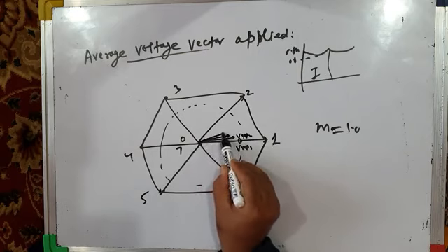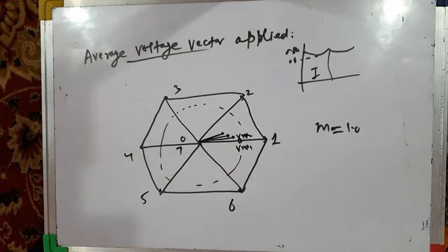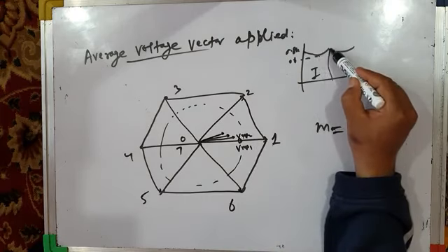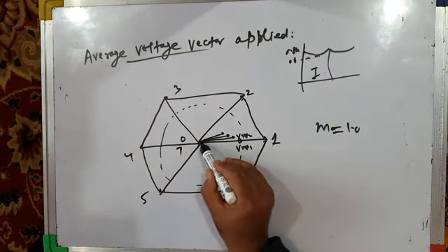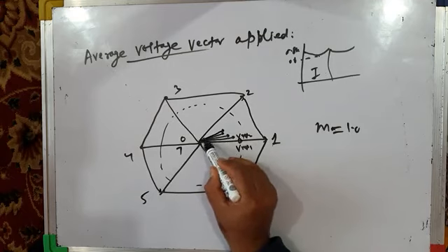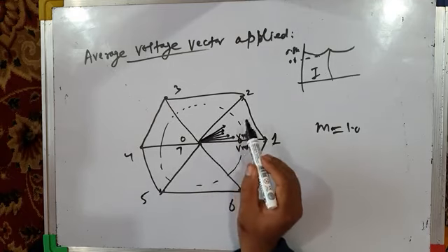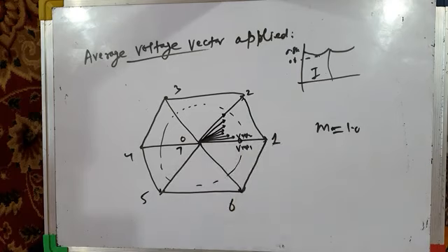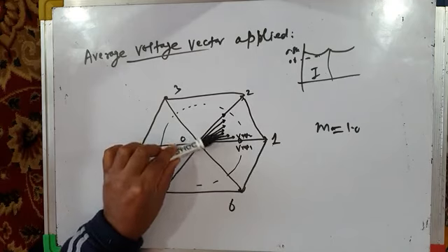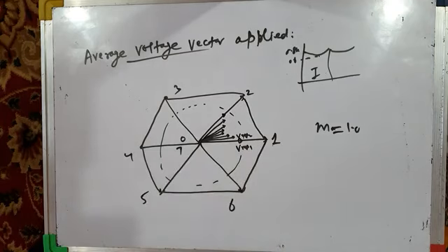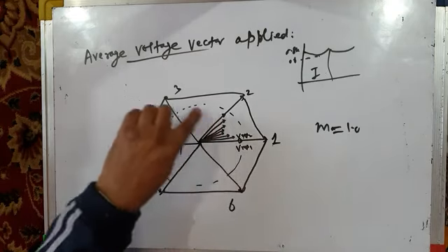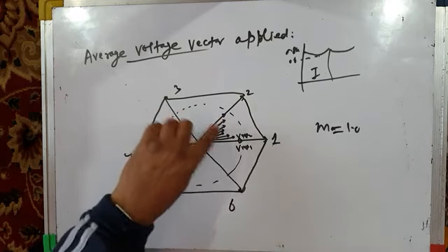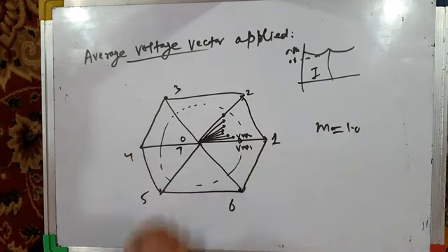Its magnitude is minimum at alpha equal to 30 degrees. Then as you move from 30 to 60 degrees, its magnitude again increases, and it is maximum here. So therefore the magnitude of the rotating reference vector with each sample is not constant. It varies in a sector, and it varies in a similar fashion in each sector.